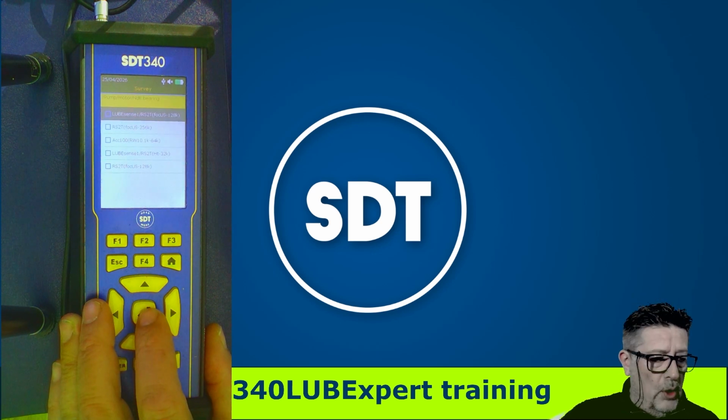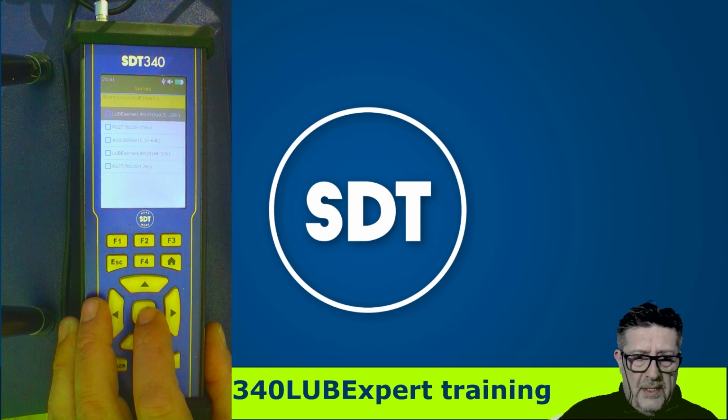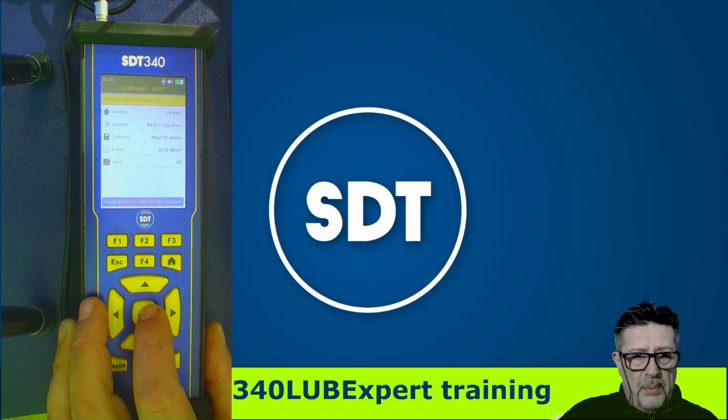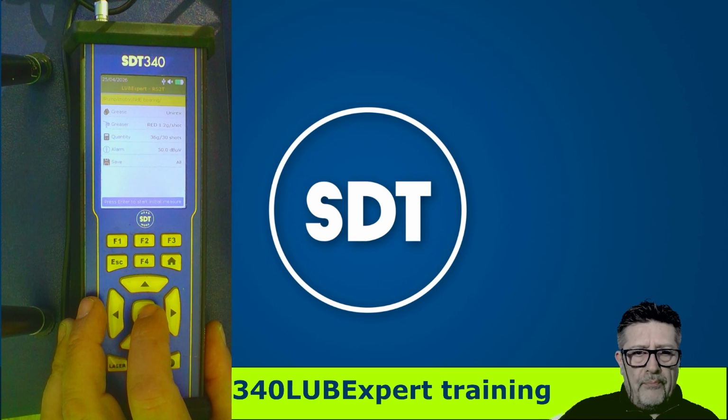When I select the motor, my first point is motor non-drive end, lubrication, and I will press enter. Once I press enter, I have a descriptor telling me where I should be, which grease I should use, which grease guide I should use, what is the adjusted theoretical quantity of grease, what is the alarm setting, and what did I select about the saving. In this case, I selected to save all measurements, all steps, time, waveform, and spectrum.